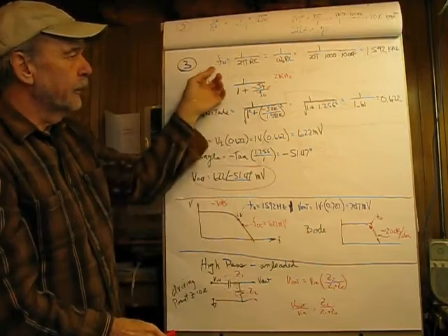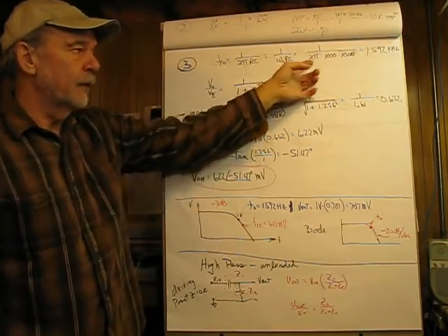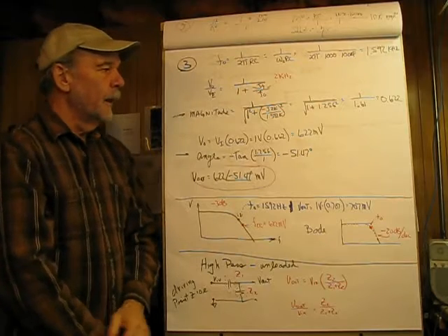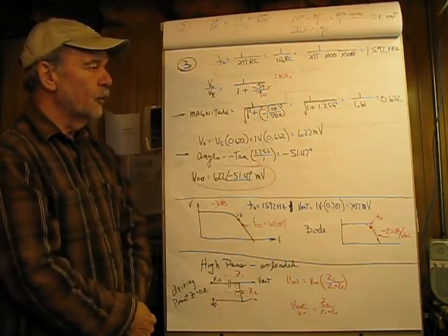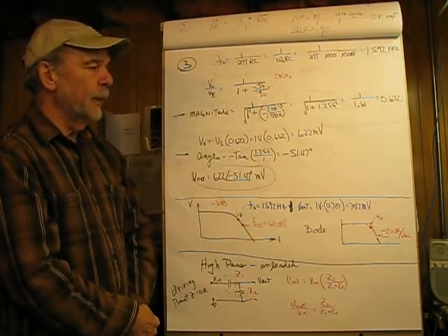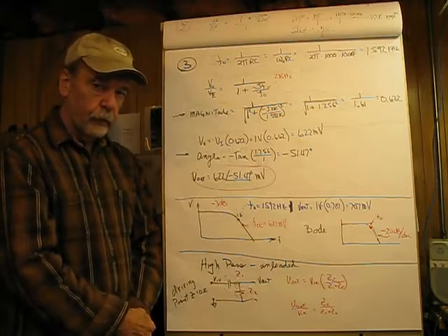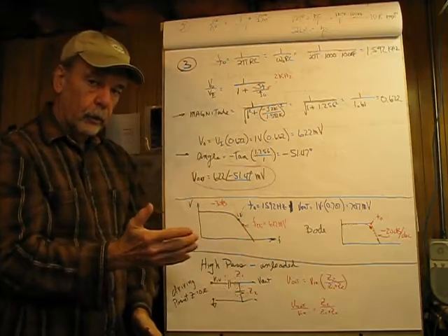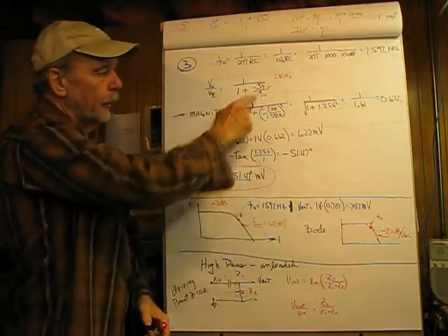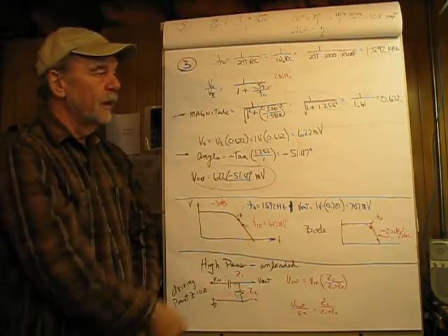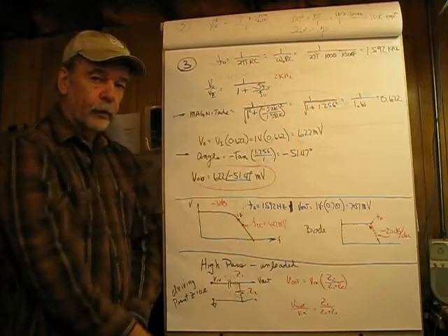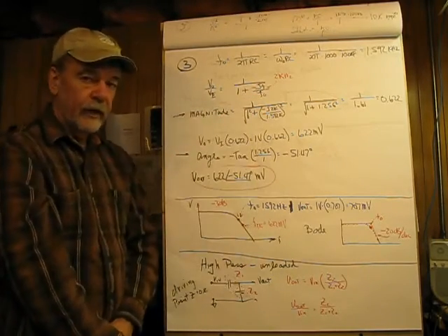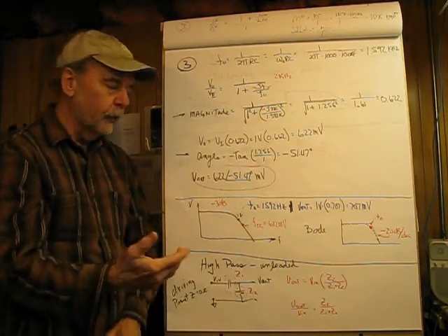And again, I've worked out F0 just for the heck of it and found that to be 1.592 kilohertz. And I'm going to now represent this, instead of omega, as a frequency. So, same form as you've seen before when we talked about omega, but in the numerator we have minus jF, and that's going to be our frequency of interest, which is 2k. And in the denominator we have F sub 0, which is our critical frequency,